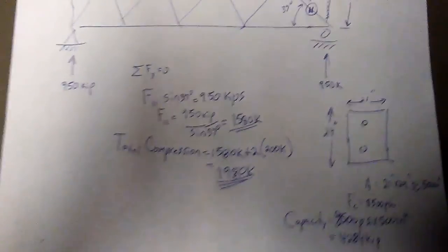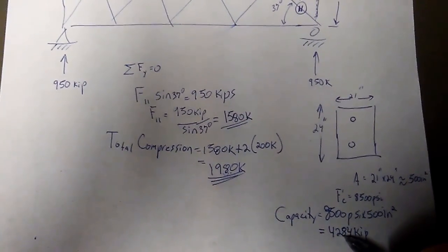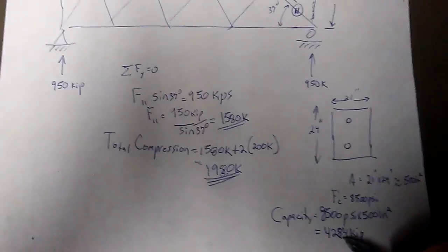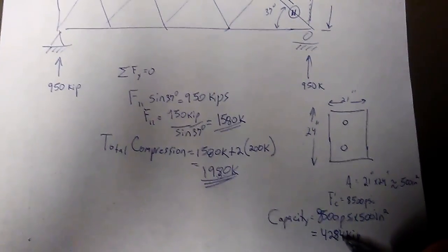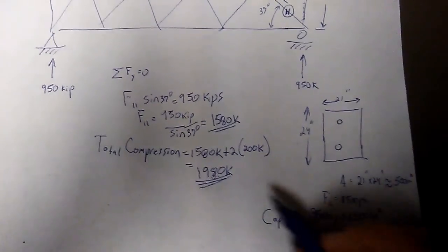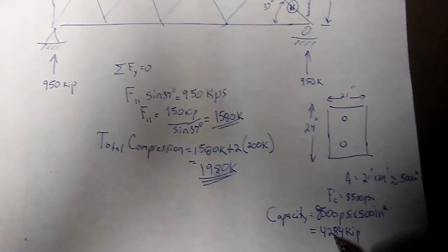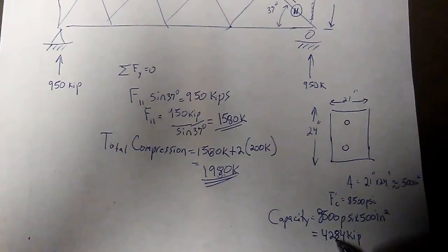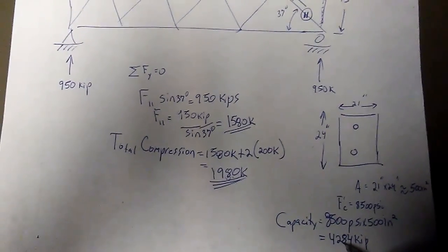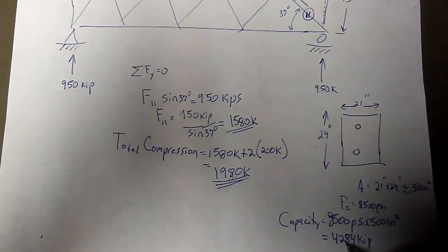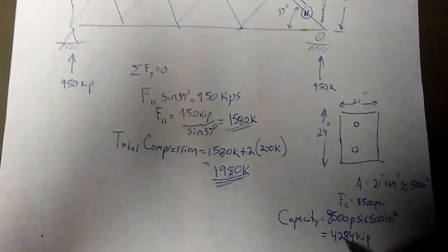Now, when you're doing a design of a member, you have to reduce this number to give yourself a safety factor. You can't just take that number and compare it to what the member is going to see, because that would be a perfect situation where everything was perfect, that the concrete was poured perfectly, that there were no voids or material defects.